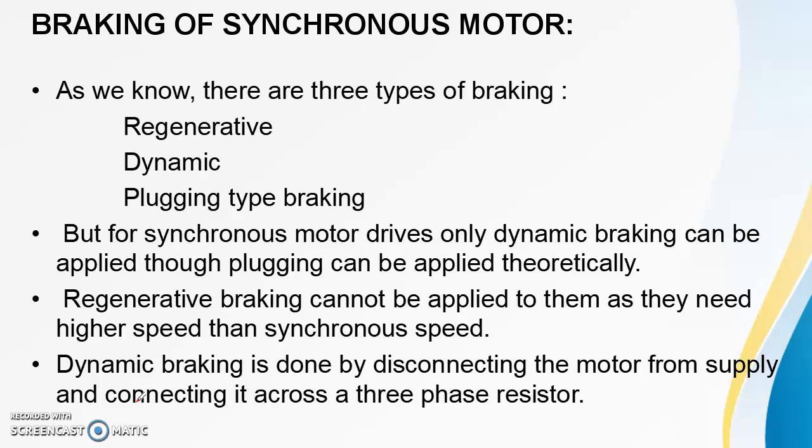Then next one is braking system of a synchronous motor. As we know, there are three types of braking: regenerative, dynamic, and plugging braking. But for synchronous motor drives, only dynamic braking can be applied. Regenerative braking cannot be applied to them as they need higher speed than the synchronous speed. Dynamic braking is done by disconnecting the motor from the supply and connecting it across a three-phase resistor. This is the simple definition of braking system of a motor.